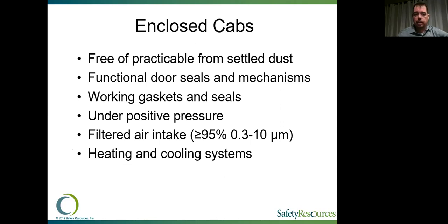The cab is isolating the employee from that dust. We've got to make sure that the inside of the cab is free of practical levels of settled dust. You don't want to come in and look like nobody's cleaned it in months and months. So if you're seeing dust settling inside the cab, that's an indication that there may be a problem with the door seals or the mechanisms or the gaskets, that we don't have the appropriate isolation for that employee.